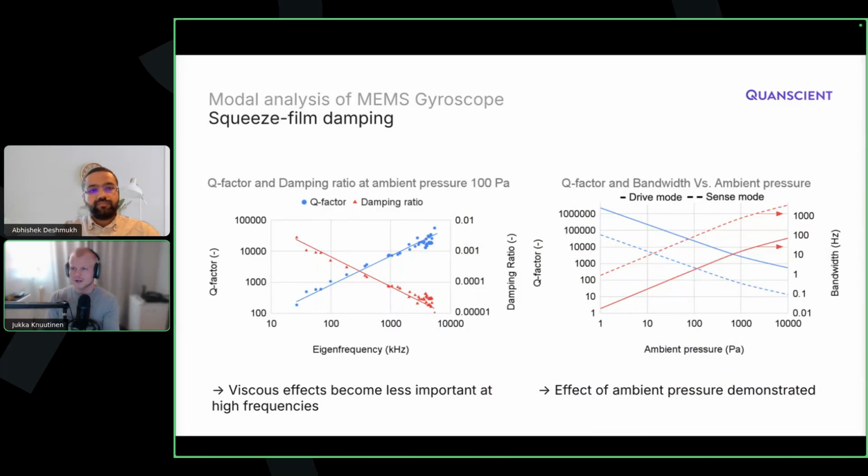What is the harmonic balance method, and what does it enable our users to do? Yeah, the harmonic balance method is essentially frequency domain analysis, but for nonlinear effects. So you can essentially simulate nonlinear processes.